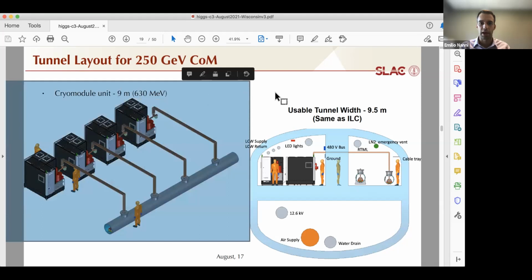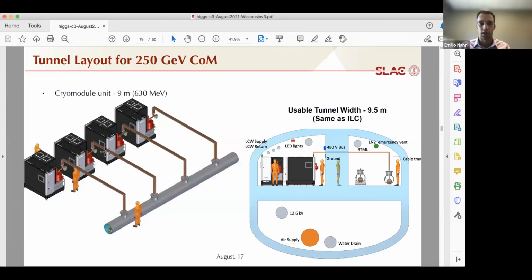They would be powered by 4 RF sources. What's shown here are actually modulators that are a catalog item from Scandinova, and these klystrons would be, for example, similar to what is being produced by Toshiba or Canon. Each one of these feeds a hybrid that splits the power in 2 and then goes over in 2 waveguides and feeds 2 one-meter sections each.